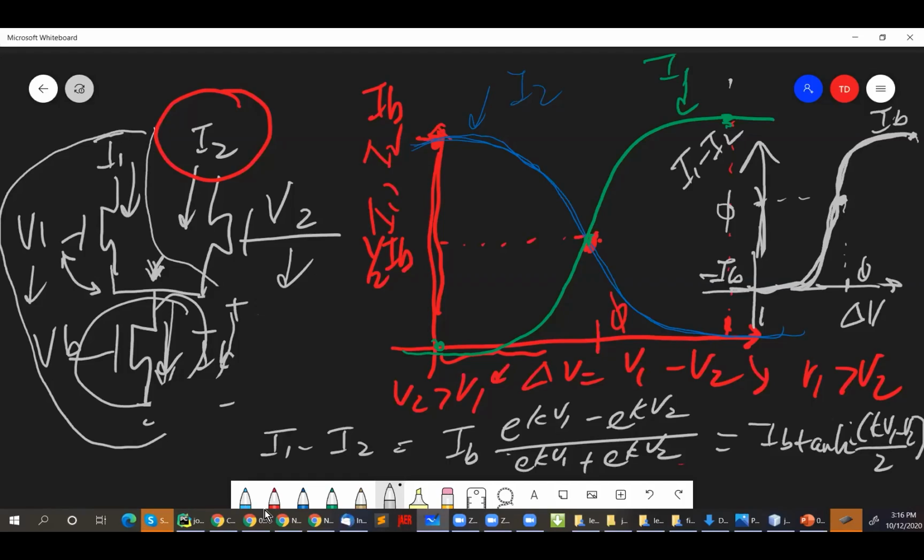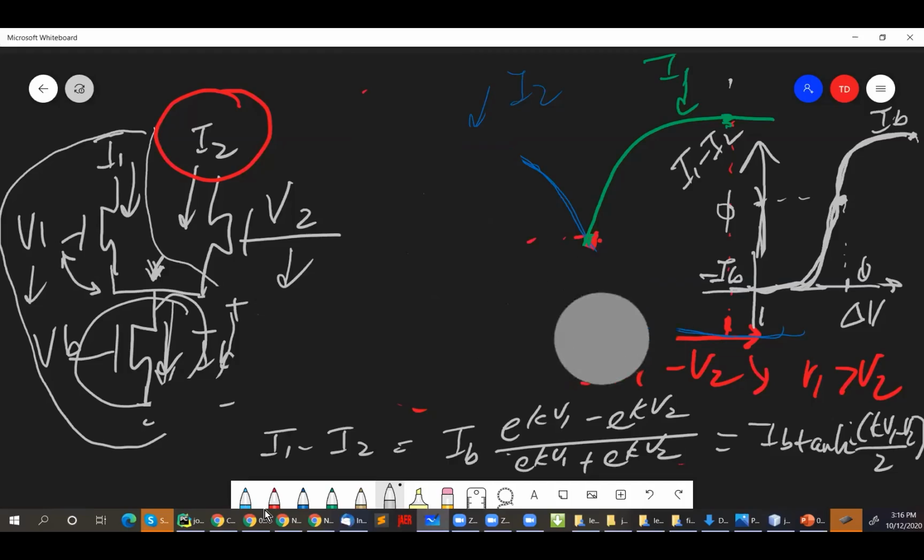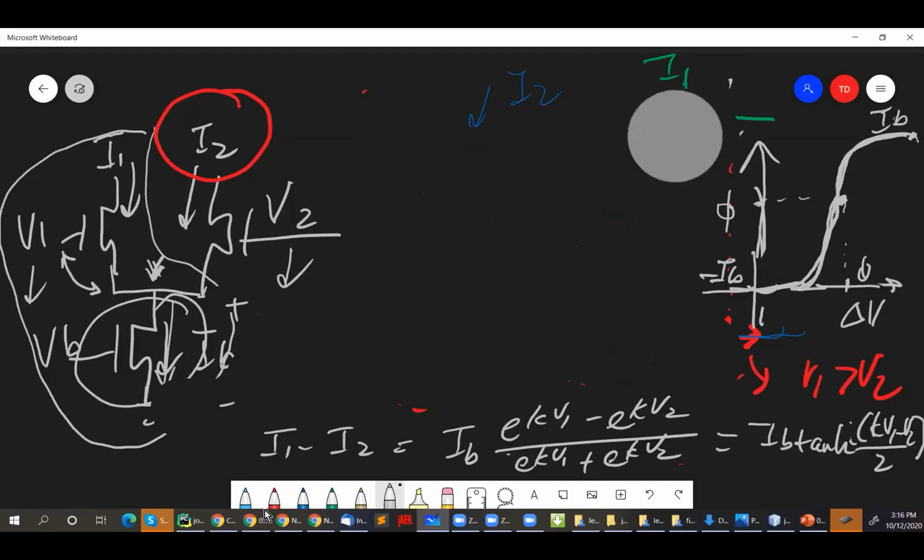All right, so let's move on. I have one question. If we consider that our system is above threshold, just because of the bottom MOSFET, do we need to use above threshold equations for MOSFET 1 and MOSFET 2? Yes, exactly. Also, the individual MOSFETs could be in subthreshold, but as we consider the whole system is above threshold, all the equations.